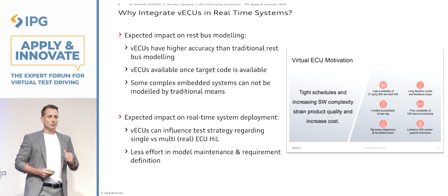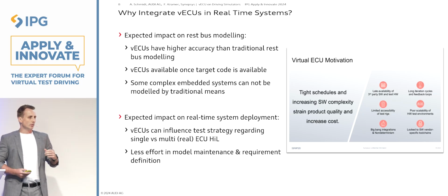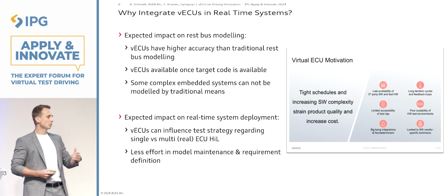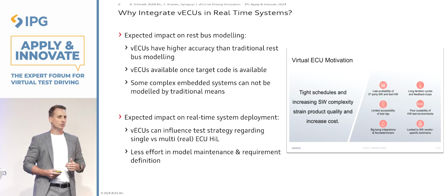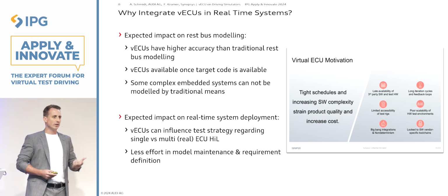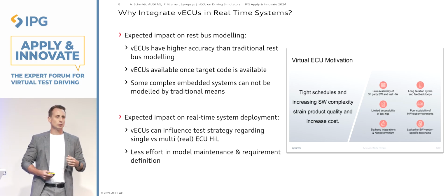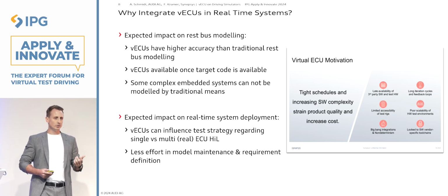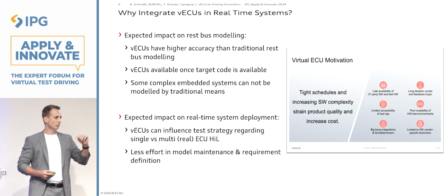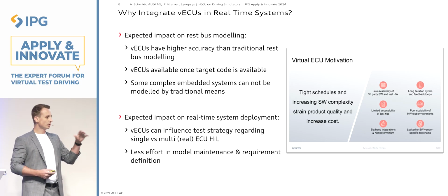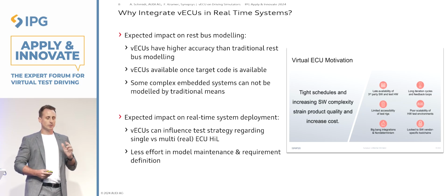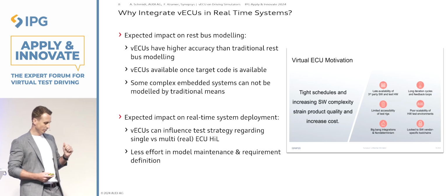So we've seen systems, let's say a big domain controller, if you need to model this, you need to cipher through thousands of requirements that have gone into building, tens of software components to be actually integrated in the domain controller. And this level of complexity is even something that you cannot model anymore, that you cannot re-implement anymore in a Simulink model, at least not with any feasible effort. So by integrating a virtual ECU, which contains real code, the real developed code for the real system, just in a virtualized environment, that should significantly reduce rest bus modeling efforts.